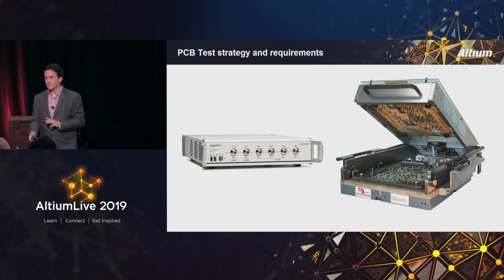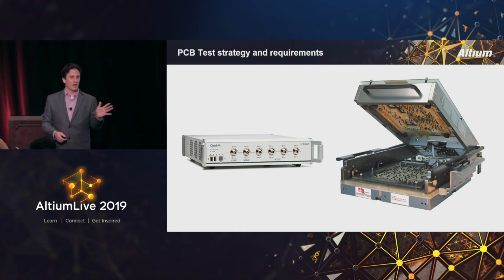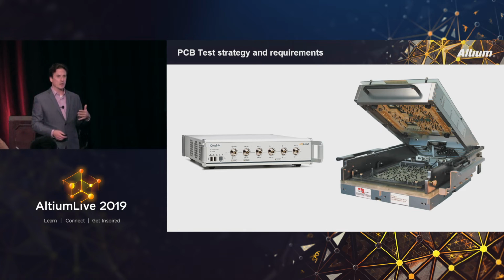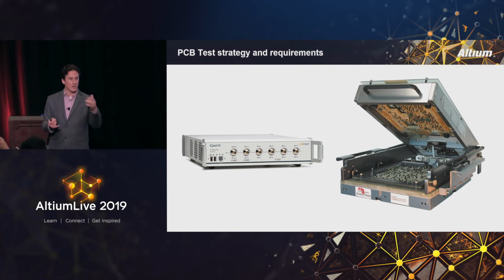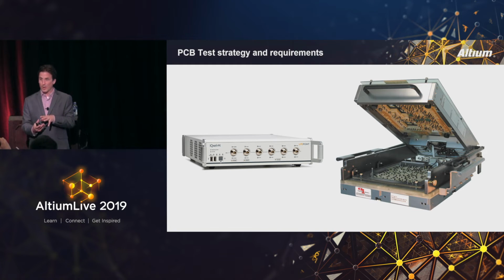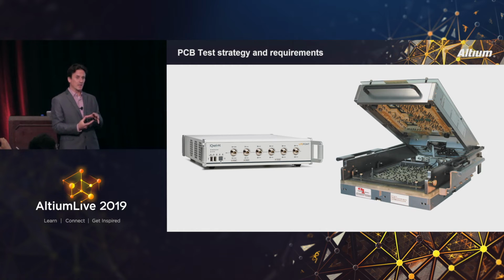RF. And I think I could teach a whole course on this here, but think about, in your test strategy, not only how are you getting to certain nets, but how are you testing your RF? A lot of times you are not doing this, it's been my experience, when the final product is designed. So you need to figure out how to test that circuit board and test the RF links on that circuit board prior to final assembly.